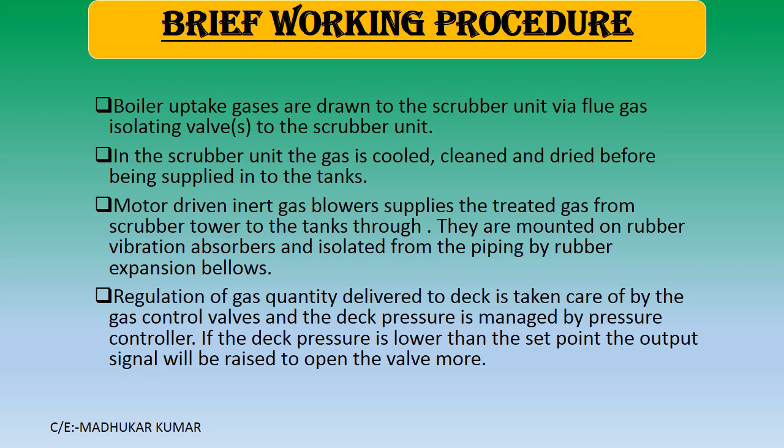Regulation of the gas quantity delivered to the deck is taken care of by the gas control valves, and the deck pressure is maintained by the pressure controller. If the deck pressure is lower than the set point, the output signal will be raised to open the valve more. That is the principle behind this.